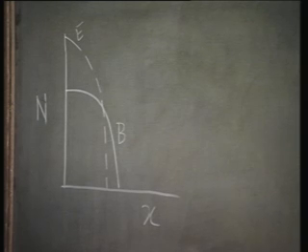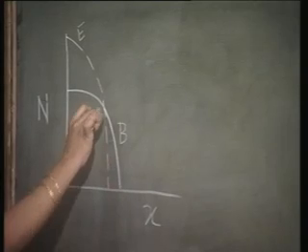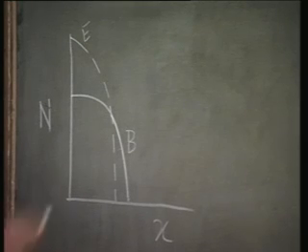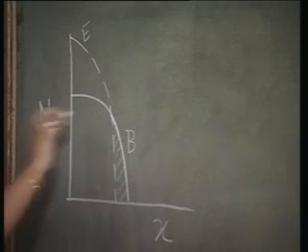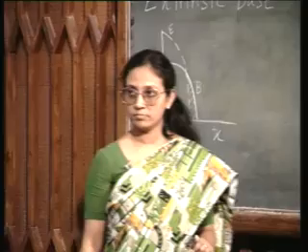Then, as far as the active base is concerned, active base is directly beneath the emitter. As far as the active base is concerned, this is the profile in the active base, right. I have only a small total charge in the active base region. However, as far as the extrinsic base is concerned, I see a much higher total charge with higher surface concentration. That is, the region surrounding the emitter has the full benefit of this implantation profile, and it has a much higher doping concentration and therefore much lower resistivity. Clear?